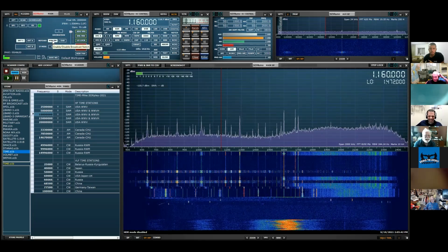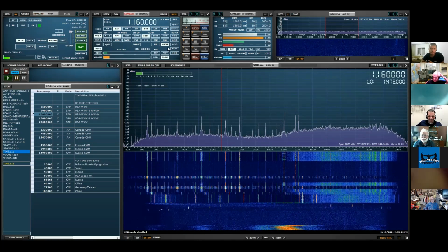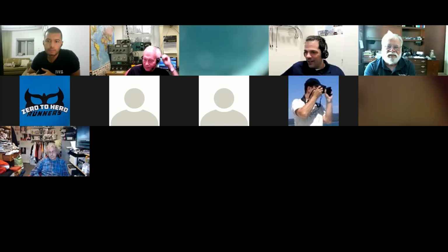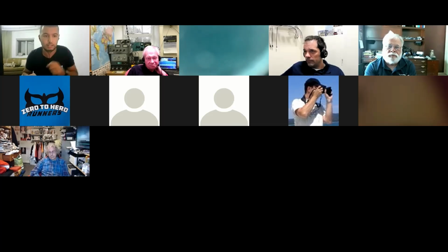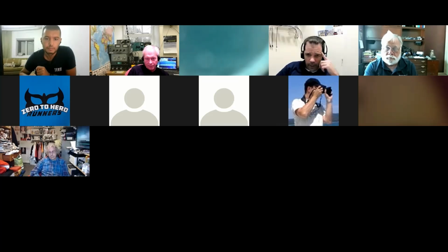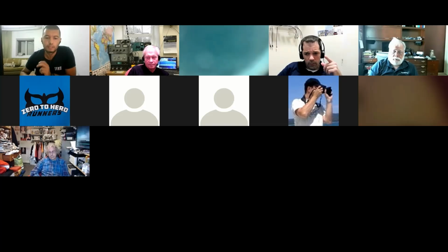Ash, where is your frequency of interest? I suspect it may be right down at VLF, in which case, if it is VLF, then I would say use a pre-selector. Yeah, mainly long wave for the moment, but I have a nearby broadcast station on medium wave, which could impact reception on long wave. Which device are you using? If it's the RSP-DX, that will specifically help you if you use high dynamic range mode for, you said long wave is your band of choice?